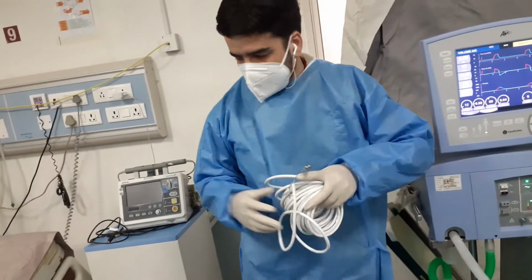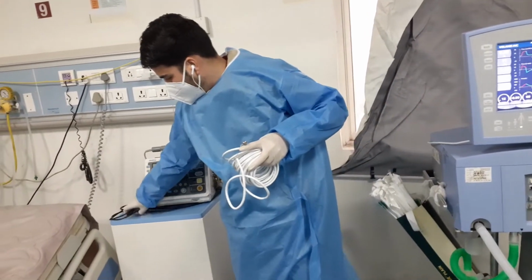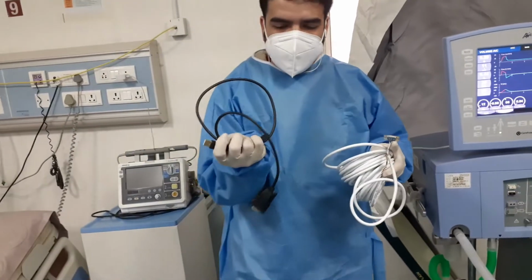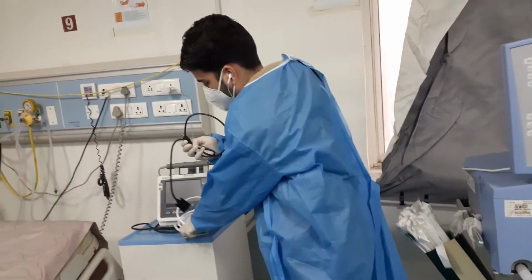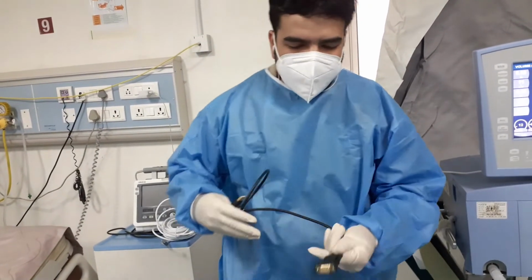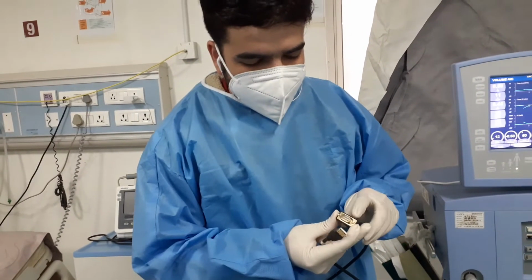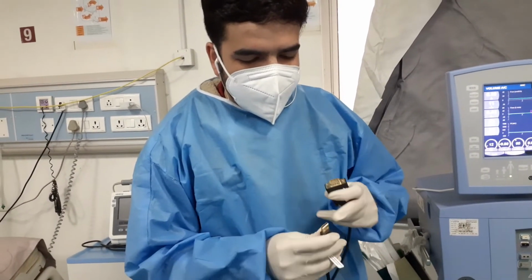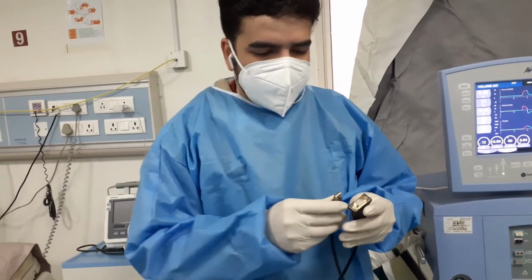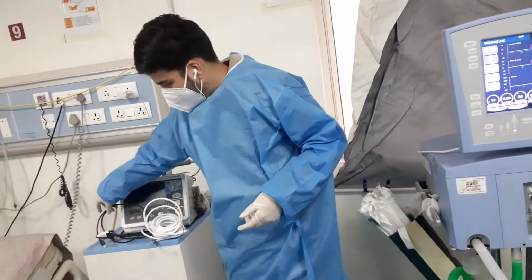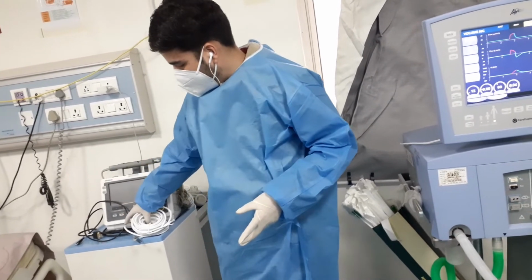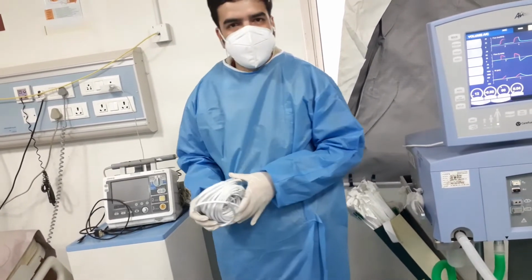After this, over this we have to attach this serial to USB converter, which is a male type converter. This will go to the female connector and be attached to the laptop. So the total electrical circuit is RJ45 to female DB9, then male DB9 to USB converter.